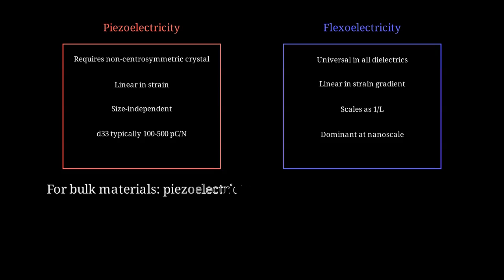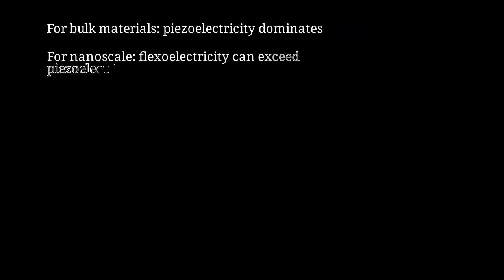For bulk materials larger than 1 micrometer, piezoelectric effects typically dominate the electromechanical response. But at the nanoscale below 100 nanometers, flexoelectric effects can exceed piezoelectric contributions by several orders of magnitude. Now let's discuss the exciting applications enabled by flexoelectric effects in nanostructures.